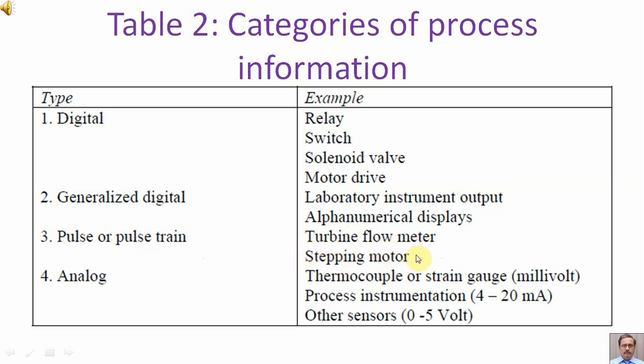stepping motor. The fourth category is analog, in which input to the computer shall be thermocouple or strain gauge in terms of millivolts, process instrumentation in the form of 4 to 20 milliampere input. Other sensors shall be 0 to 5 volts. In the next few slides, we shall be discussing these categories in more detail.